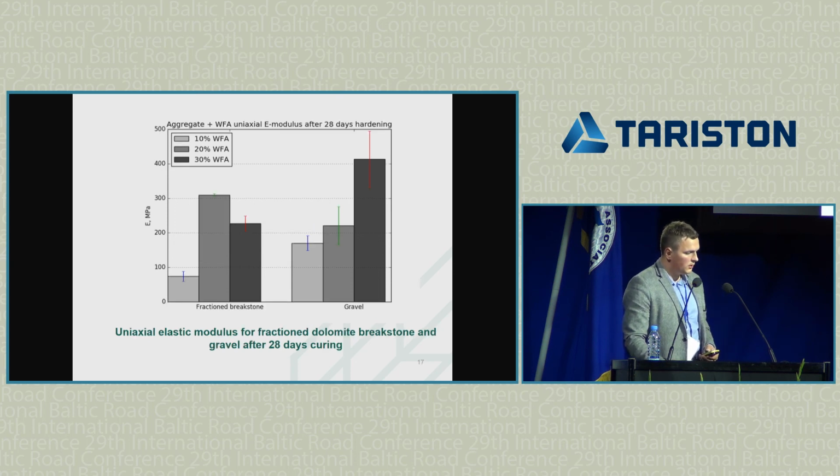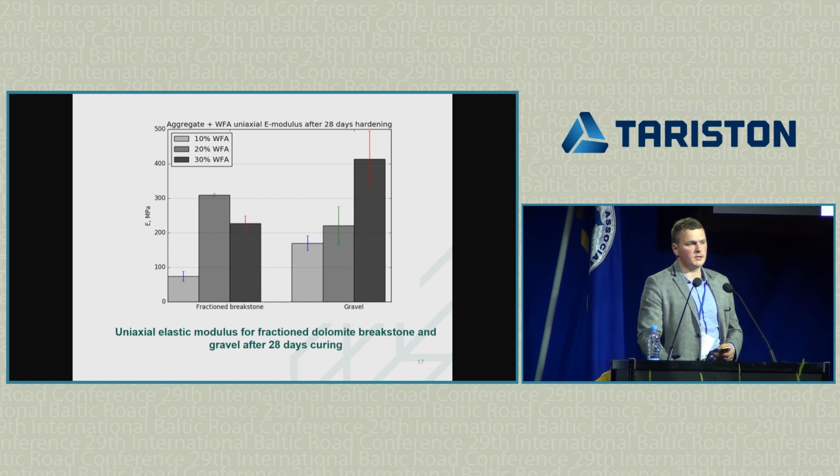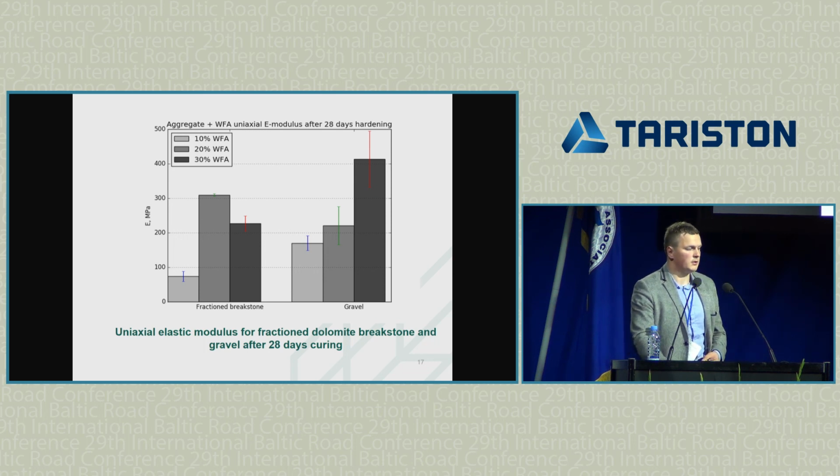Well, we actually also tested with LVDTs attached to the sample. We also tested the one-dimensional E modulus. Although in the literature, very often for the design, it's used just the unconfined compression strength multiplied by some constant values, we tried to determine this modulus by LVDTs.